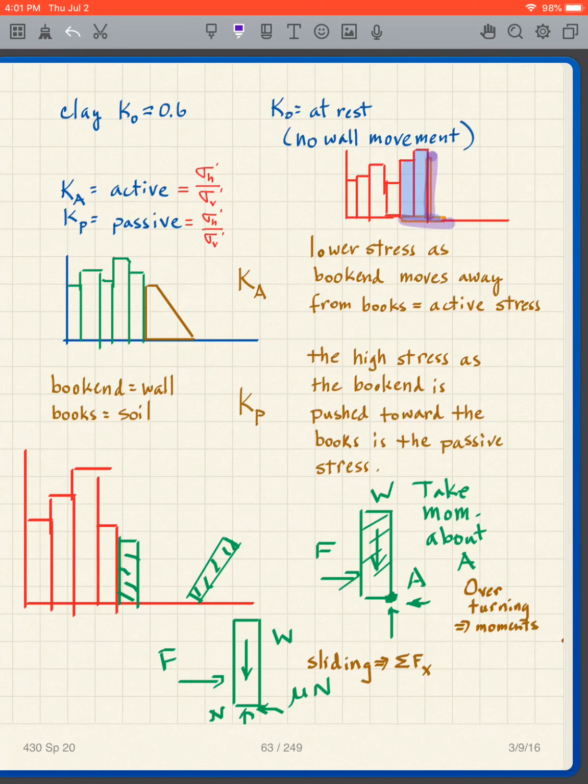Well, we have to consider the soil that's sitting here. That's basically part of our wall. So that is included. In a sense, we're making this kind of wall into a gravity wall. Although the wall itself is not heavy, we are actually relying on the soil sitting there to act as part of the wall and give us the gravity action.